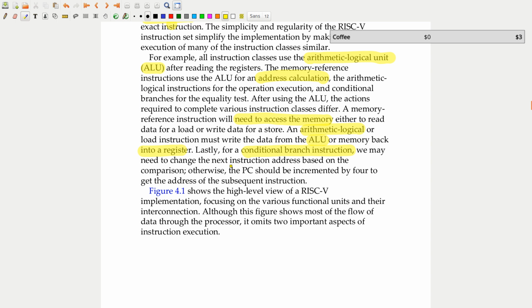With the arithmetic instructions, we passed two values to the ALU, and then wrote back into our register file some other value that we calculated. But with the branch instructions, we do some calculations, generally checking an equality, at least in this case, and then that result is going to change the program counter this time, not necessarily something in the register file or memory.